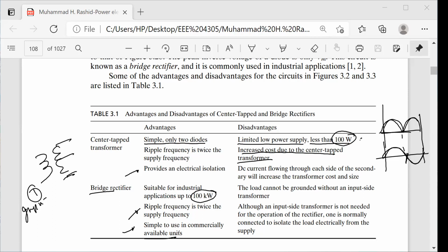Sir, if we use these rectifiers, we are actually using them for DC output, right? But sir, if we get the ripple, isn't it actually bad for our electrical devices? Of course, you will have to use a filter, capacitors, mainly capacitor. This capacitor will give you a smoothed output like this. Also inductor and capacitor, a low pass filter.